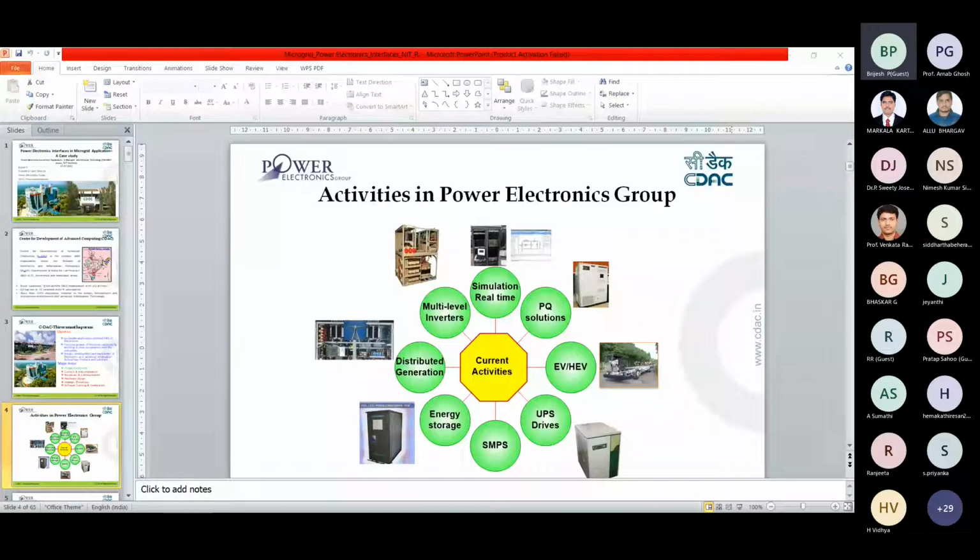Basically, it is a localized grouping of electricity sources and loads. Normally, it will operate in synchronism with the main grid. Sometimes, if something happens in the grid or there are planned interruptions, it can act as a standalone system also. But when coming to microgrid installations, most of them are standalone microgrids, especially due to the application in that area.